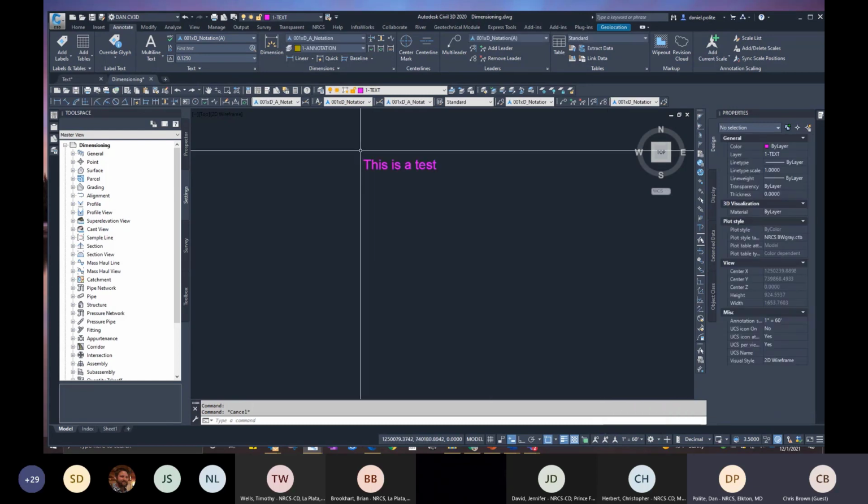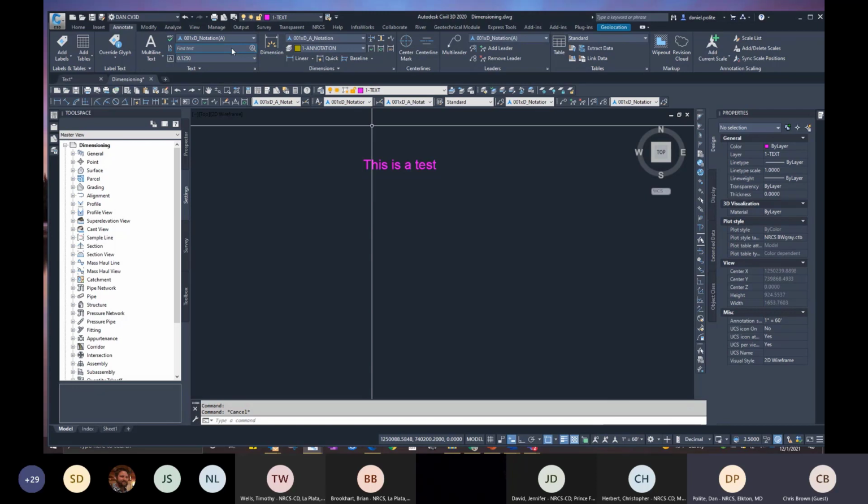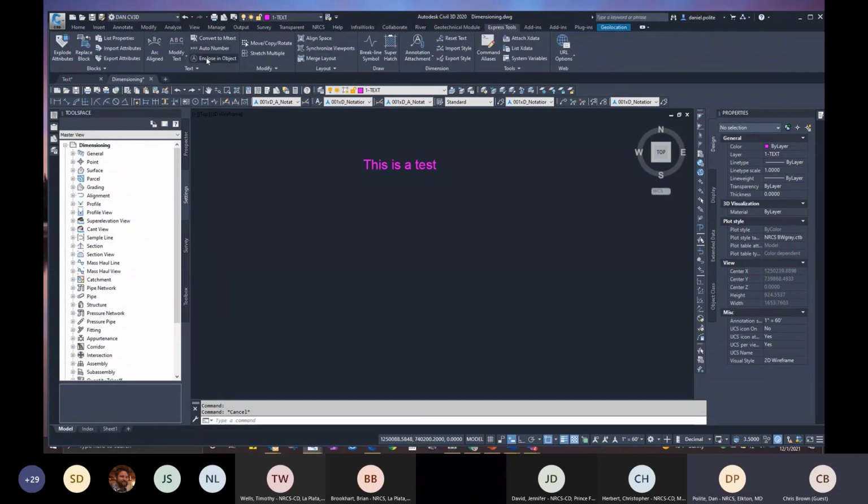I'm going to draw a box around this. Now, a couple ways you can draw a box. Actually, I believe it's in Express Tools, Enclose Object. You can select it, hit enter. You can do an offset distance. You can do the default of 0.35, it's fine. And you can do a circle, slot, rectangles, and we'll just do a rectangle for now.